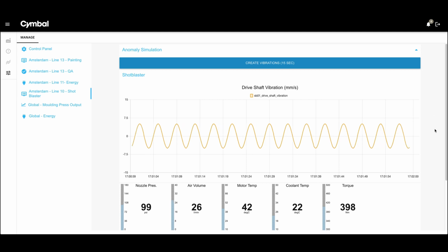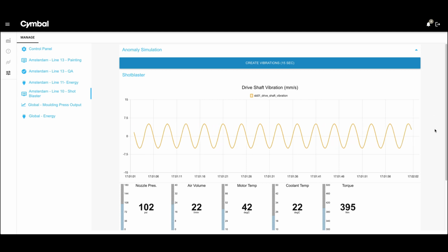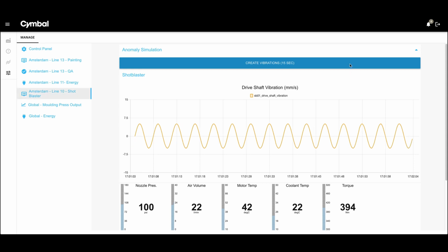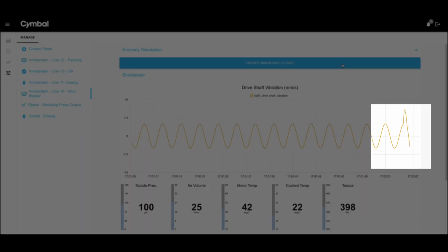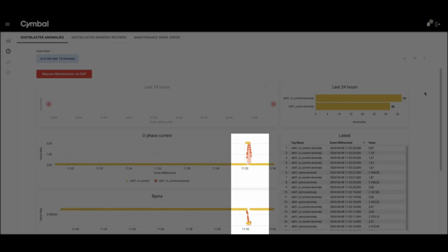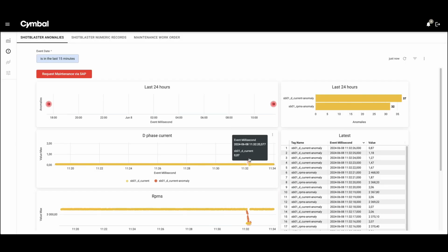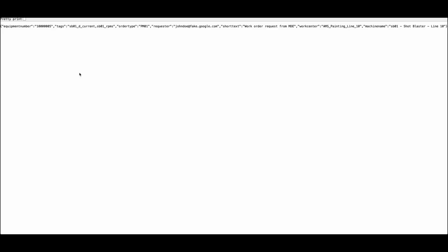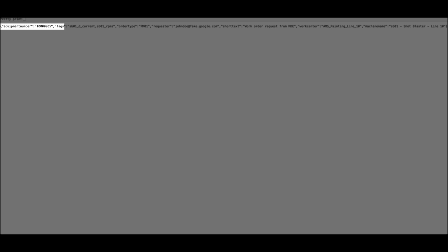Vibration sensors can be mounted on the equipment to stream shaft vibrations of the motor to MDE. Here for the demo, I will be manually simulating some anomalies in an otherwise perfect stream. MDE can have either machine learning models or statistical rules to detect any anomalies in the pattern of the received vibration stream. If an anomaly is detected, it's an event in MDE and a maintenance request can be raised by the plant manager. This can also be automated, as in when a request is placed, a maintenance notification with equipment details can be sent to a Cloud PubSub topic.